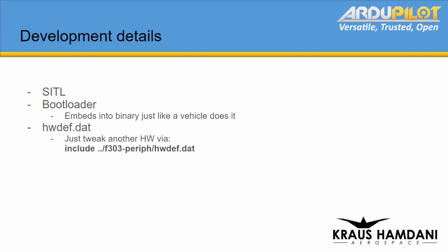And the bootloader itself is a little bit bigger than normal bootloaders, because all the interaction on here is happening through CAN. So the whole CAN stack has to be in there. That pushes the file size above 16 kilobytes. So in most of our targets, like F4s, 16 kilobytes is a block, so we can run it that big.